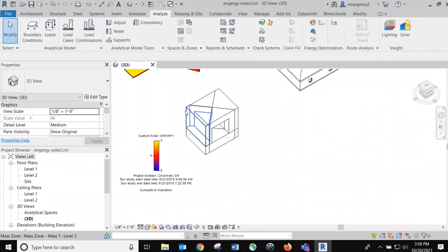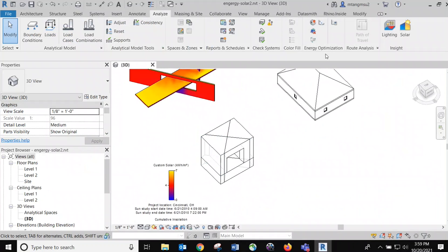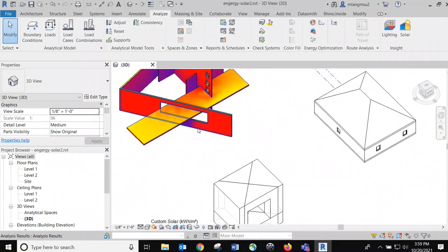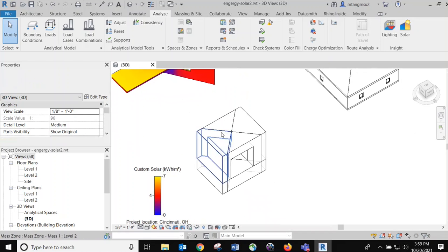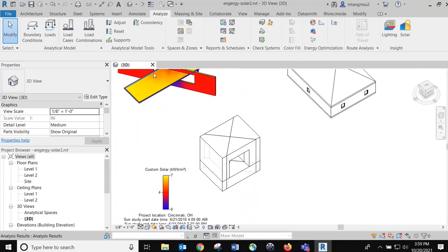All right, so I think that's a quick demo for the energy model. As you can see, once I send out the energy model, the color disappeared, the heat map disappeared. It's just because you have two models overlapping each other now. You have the energy model on top of your 3D model. So if you want to see the original color, you have to delete this energy model.